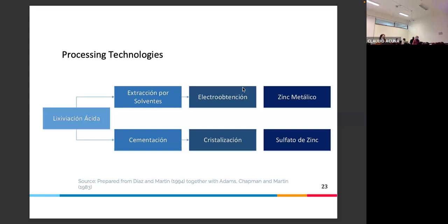And then when we are in level 4, it's a larger process. It can be 5 liters, 10 liters, still bench, not 2% anymore, now 10%. We are exploring the effect of solid content, volumetric solid content. We are exploring more realistic conditions, but still it's bench scale.